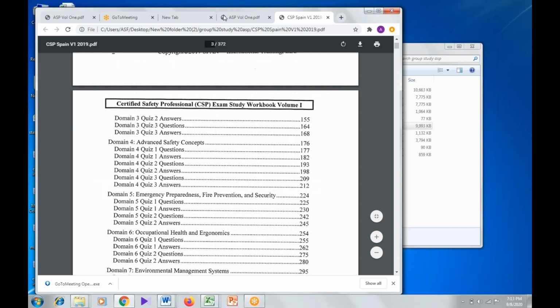But for chlorine dioxide, it is 1000 only. It is not possible to remember all of this because they are very huge schedules, very huge schedules of requirements for OSHA to be included inside the PSM. So for the OSHA PSM rule, chlorine is 1500, and under the EPA RMP rule it is 2500 pounds. So this is the difference.